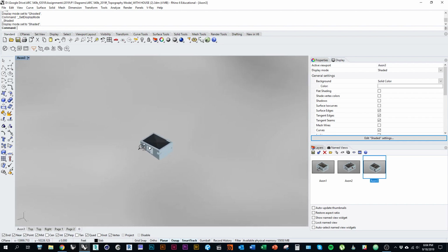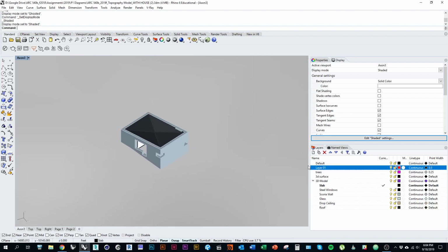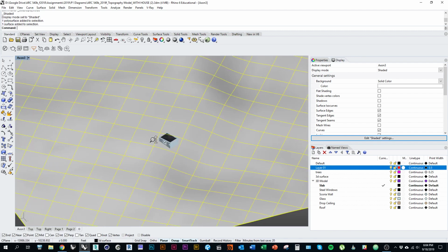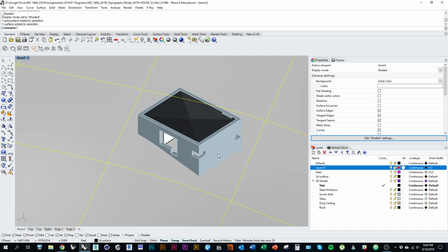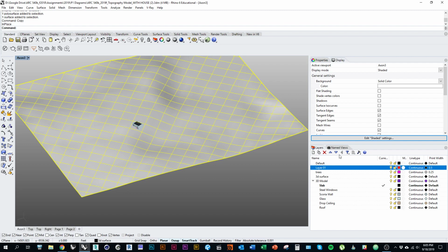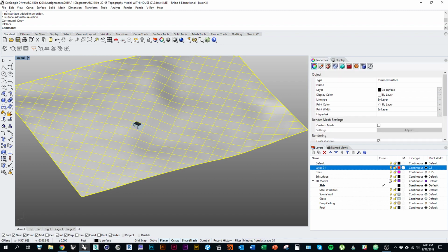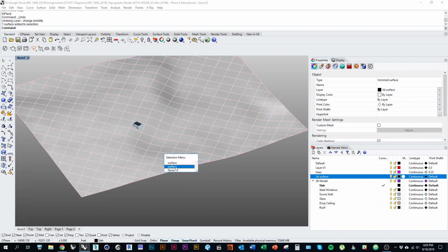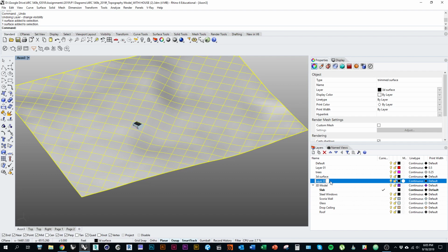Now I'm also going to do a little bit of work to prepare my file. I go back to layers. First of all, I want to trim my topo surface. So instead of trimming the whole thing, I'm actually just going to make a copy of it. I'll use the command copy, hit the option in place. Okay, and let me just see what this is on 3D surface. Oops. So now I have two topo surfaces here. I'll make a new layer and call this my drawing topo.